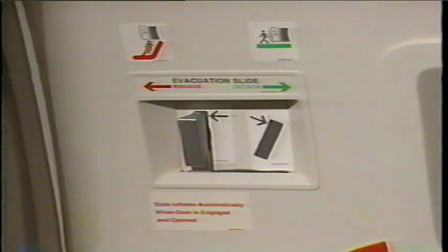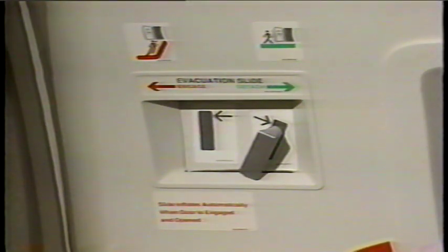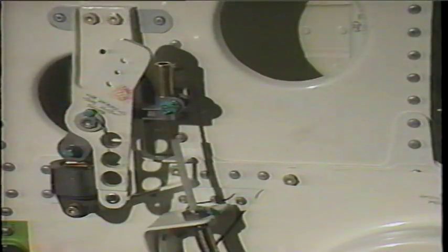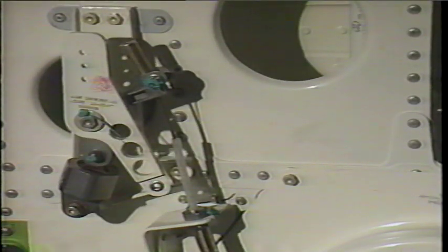When adjusting the disarm cable for the passenger doors, the objective is to remove the slack to be sure that the disarm cable will pull the mode selector lever to the detached position when the external handles are butterflied to open the door. The initial rigging is done with the system set in the engaged mode. The mode selector lever is positioned to the engaged mode, and a 3/16" diameter rig pin is inserted through the rigging hole in the handle base into the hole in the housing.